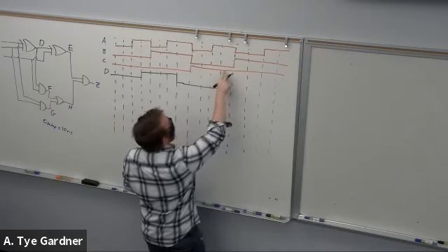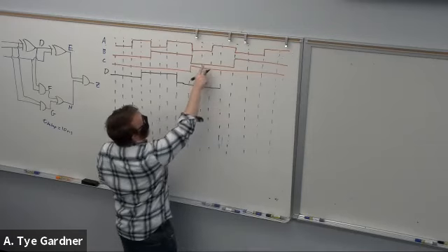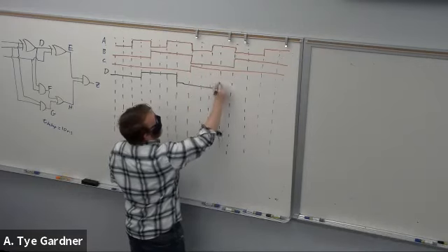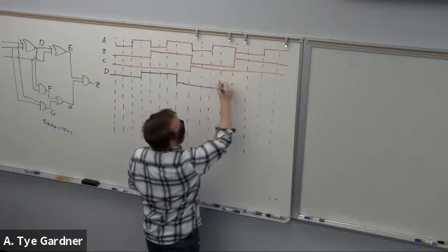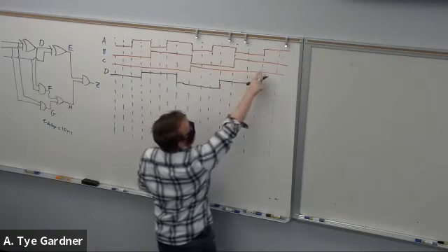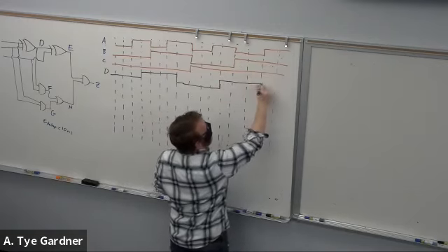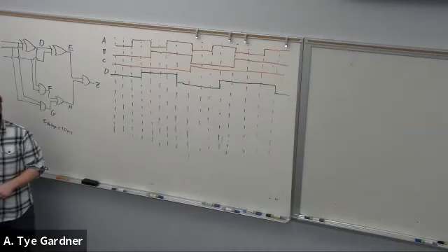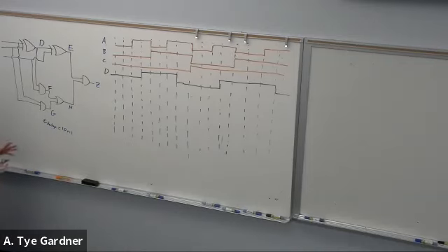And this is actually kind of interesting, because at this point they're the same, they're different. So it rises, they're different, still different until that one, they're the same, and then it drops. Okay, so that's the easiest case. There's one gate delay that I have to worry about from there, and the A and B's have the same gate delay. Now we can do E next.